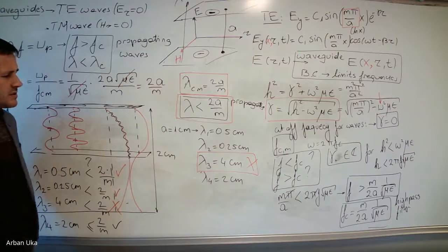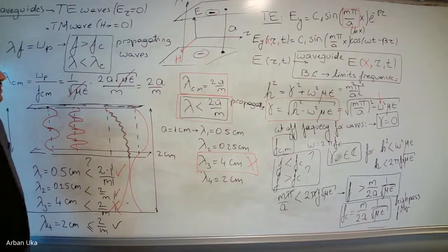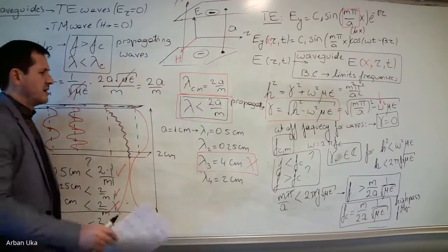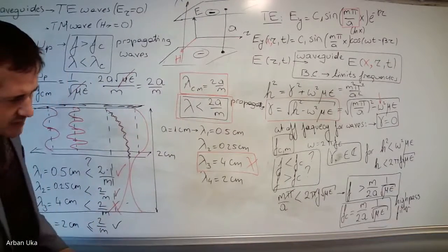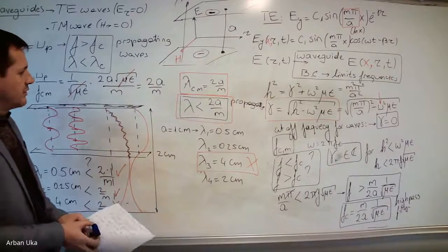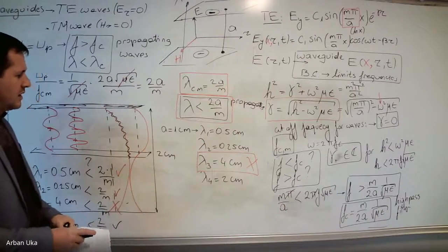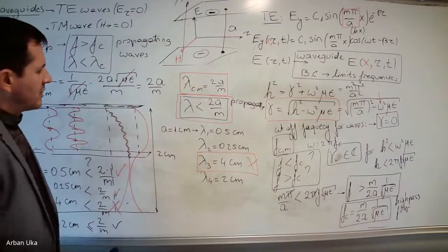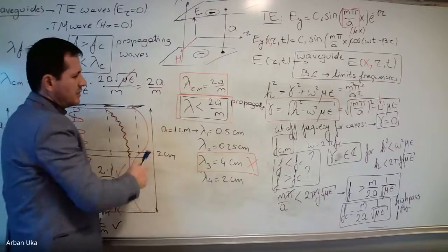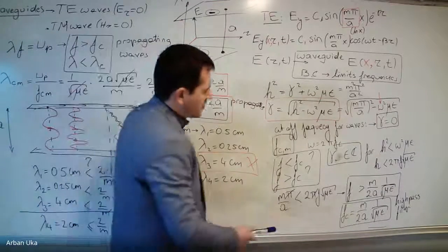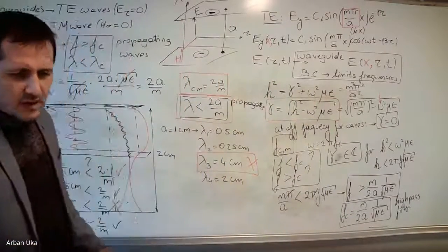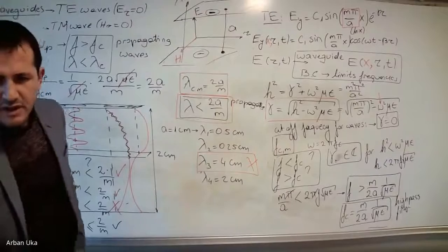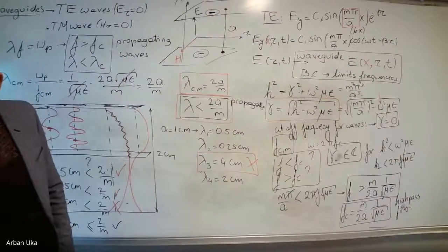So sometimes for students, you can use both techniques, but often students might find this approach more intuitive, because they can simply say, well, it doesn't fit. I mean, the wave is bigger than the waveguide, so you keep it out. This is one way to think about this. Another way is you can simply call it a high-pass filter, which means that it is going to allow only frequencies that are larger than the cutoff frequency.